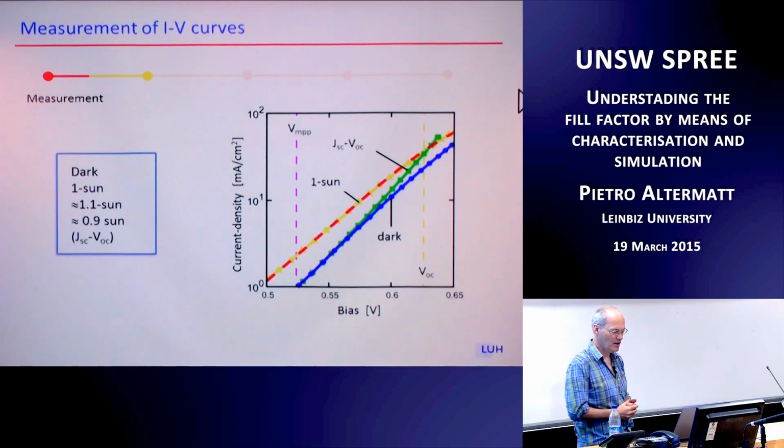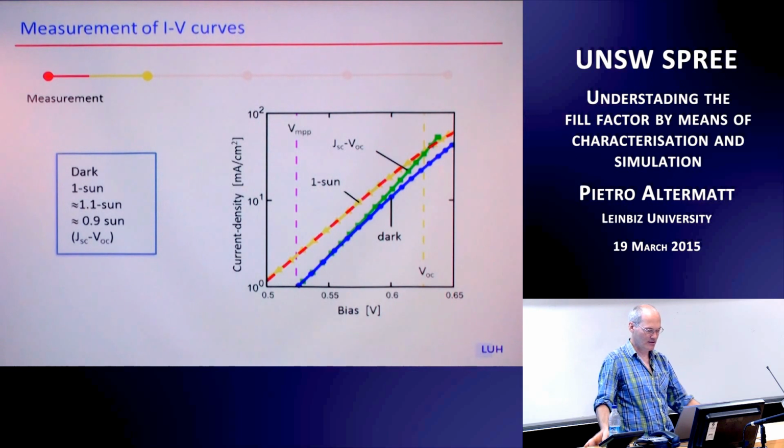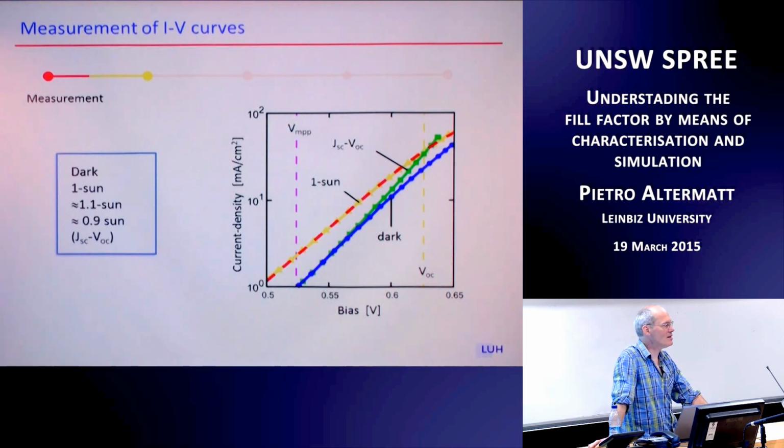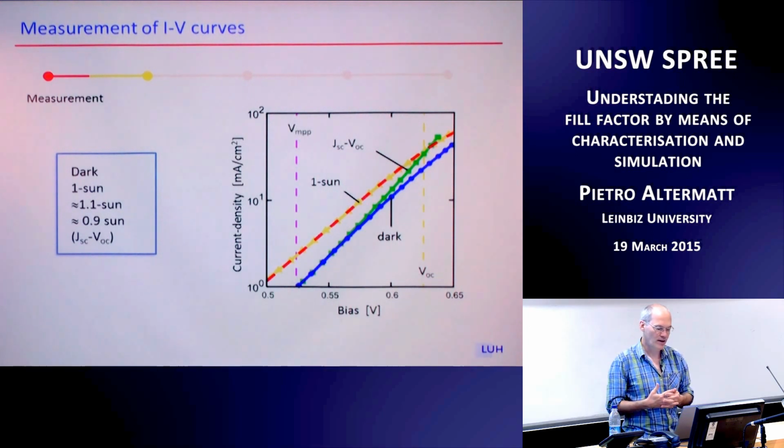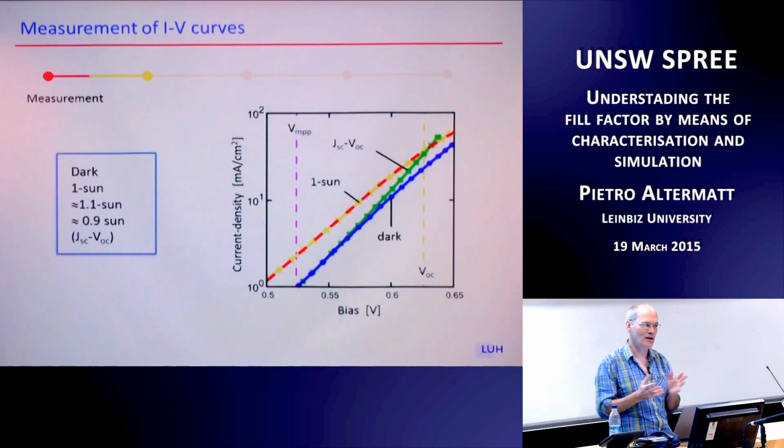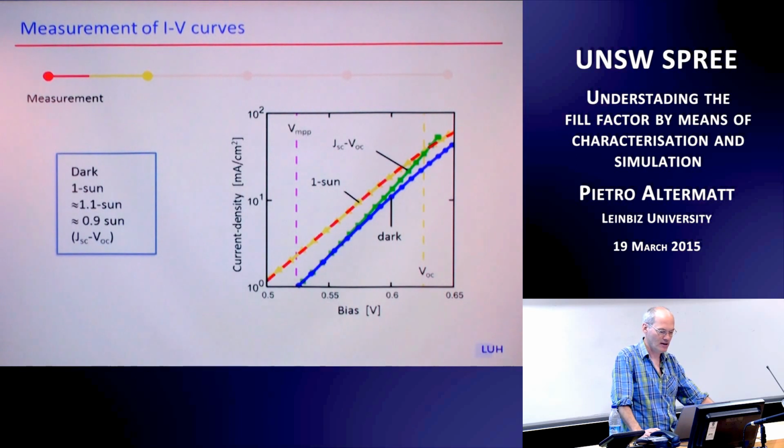of the fill factor. So people in standard measure the dark IV curve and one sun IV curve. Some measure JSC-VOC curve. But I also recommend you, when you're interested in a proper analysis, to measure both an IV curve that's a bit above one sun and a bit below one sun. Often statistically, and with the error analysis, it turns out that about 10% variation is quite optimum, but it can also be more if you need bigger differences between the suns or so.